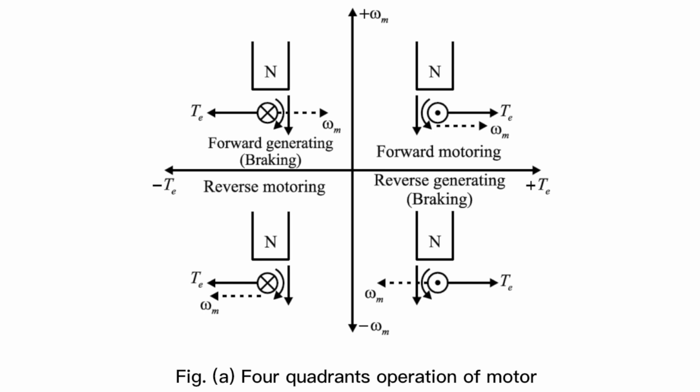Field reversal is necessary with some forms of rectifier control. Both AC and DC rotating machines can operate across all the four quadrants, but DC machines transition between quadrants more smoothly and perform reliably throughout their entire operating range. So, DC machines are preferable.